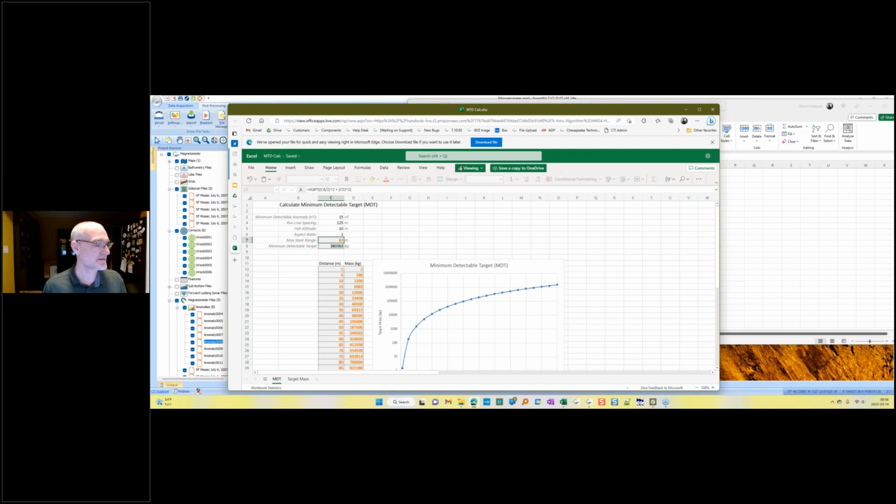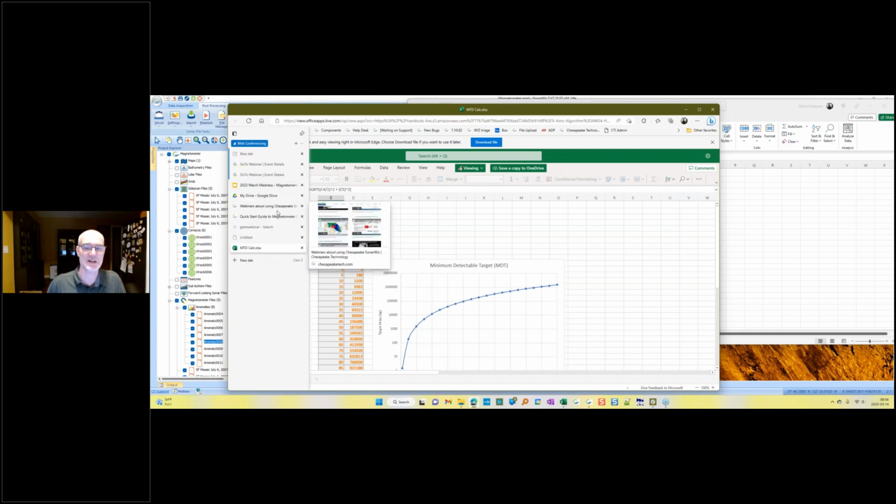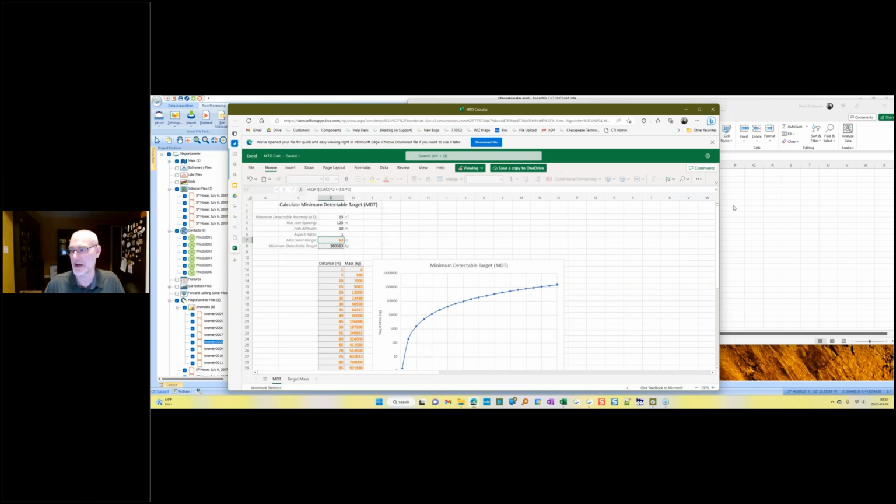It says, what if you do not have a known target to relate to? Do you assume the target is directly below the magnetometer? No, so if you don't have the known target, all you can do is assume. The equation does assume that the target is at the minimum distance. So for the minimum detectable target distance, the way I showed you to calculate it, we use the slant range from the fish to the center of the lines.